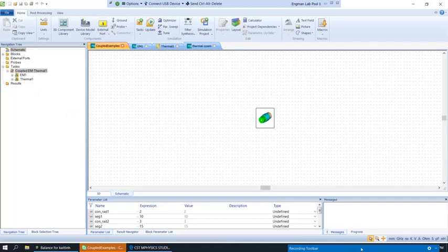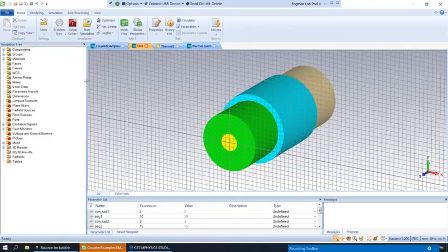All right, so the first thing we're going to do is go to the EM project. This is the microwave studio, the electromagnetic side of this project, and we need to check a couple things. So the first thing we want to check is what field monitors have been defined. So we can see some field monitors have already been defined for us. It has automatically defined the E field monitor, H field, so electric field and magnetic field, and then this loss monitor.